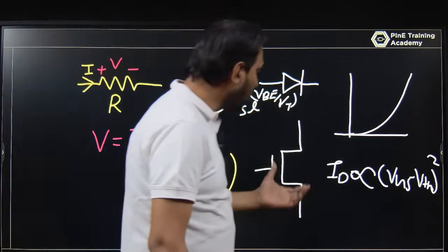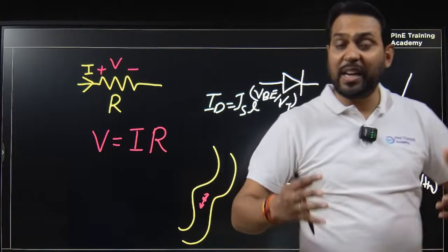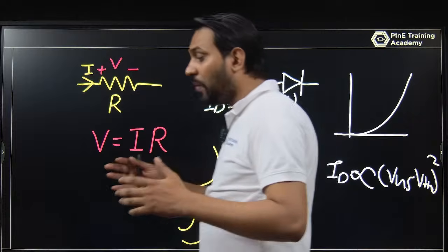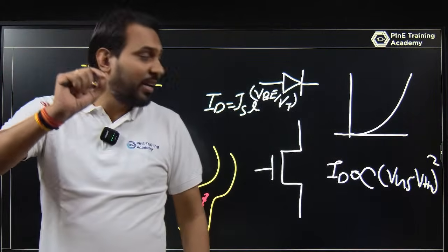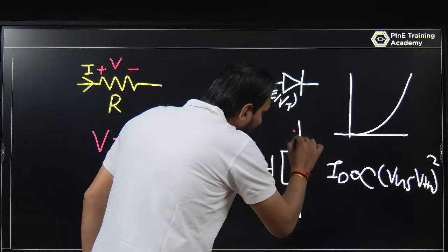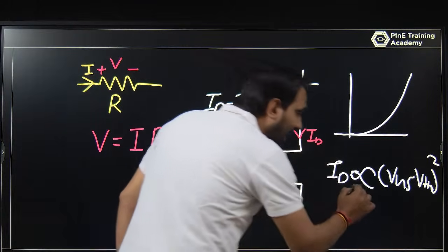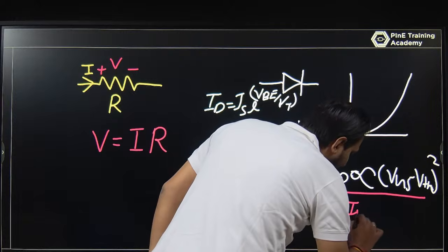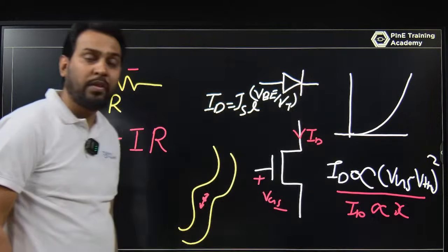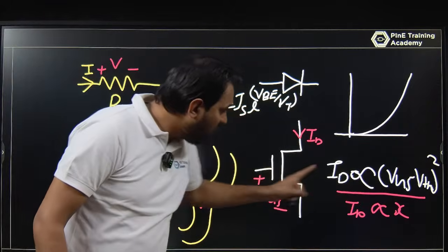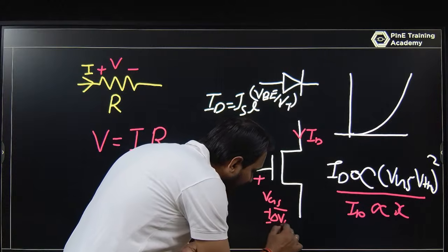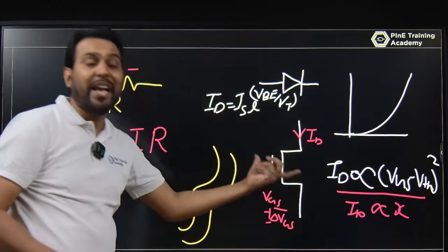So when we are talking about the MOSFET, it is basically a non-linear circuit. But at an exact point, let's say you have some drain current, some X value. At that value of VGS, if I change by a small value, plus or minus delta VGS, it looks like a small signal model.